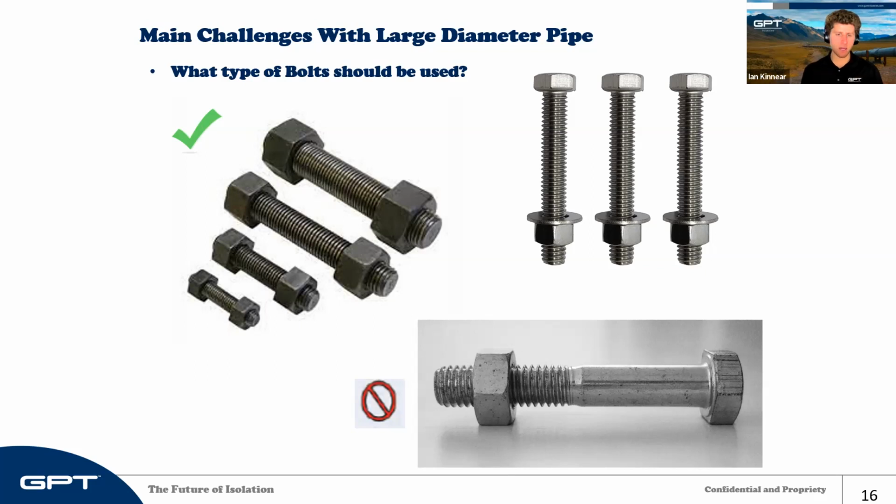The entire kit becomes compromised. Now you just bought an isolation kit that can't isolate, or you bought a bunch of bolts that can't be used with the kit. Either way, it's just an expensive thing. Just know up front, we want these bolts to be threaded all the way through, and use studs whenever possible. Studs are the best, the highest recommendation that we have.